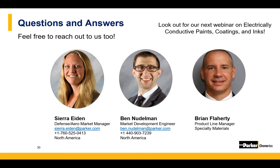So I would question what he means by silicone is problematic. Usually when I hear silicone is problematic in their factories, it has to do with coating operations in their facility, and they're worried about silicone contamination and the fish eyes. Anytime you get silicone contamination in a coating, when you go to spray that coating, a lot of times you'll see this surface phenomenon, which people refer to as fish eyes, and that's silicone contamination in the coating.